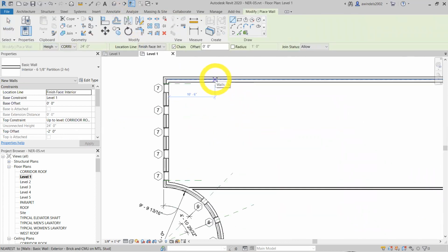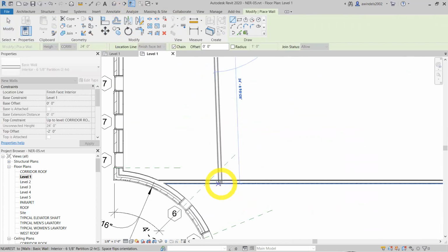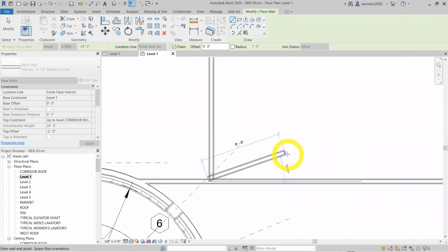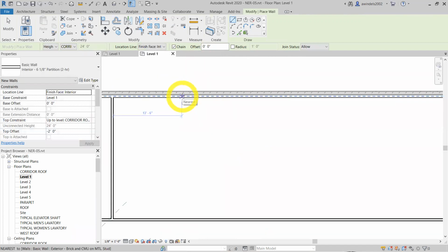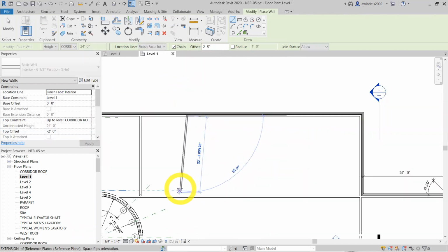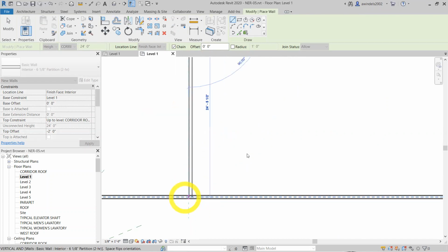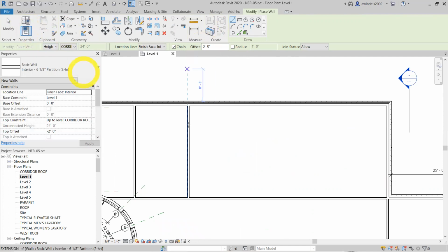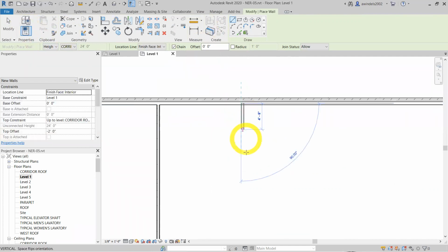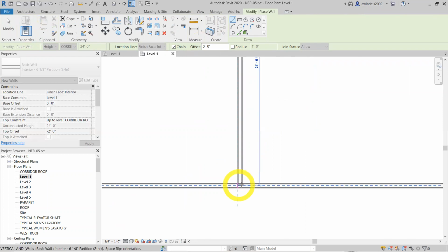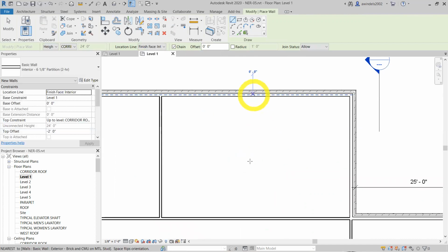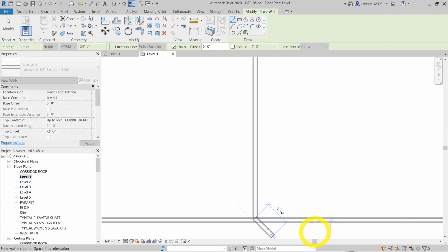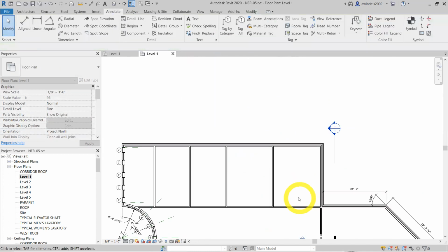And now we're going to place more of these interior partition walls at unequal lengths. Just kind of wing it here. Goal is to change them later. So don't try to get them precise. Just kind of freehand draft them in here. Do 5 of them. Keep the command open as you go. Just keep drawing them. Do one more. Right here. They're all joined. We have 1, 2, 3, 4, 5 open spaces.